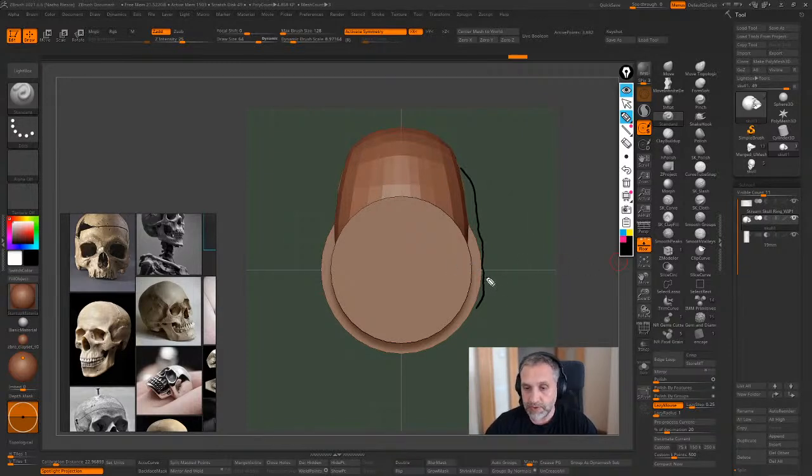So that's the reason why I use this. So try to avoid going further from this point. Maybe from this point, we should be around less than 3 millimeters, and from here and above we can go higher, 3 millimeters. And at the bottom of the ring, from this point to the surface of the ring, it's going to be a decision depending on the kind of material that you are going to cast the ring in. It's going to be cast in gold or in silver, the same like here.